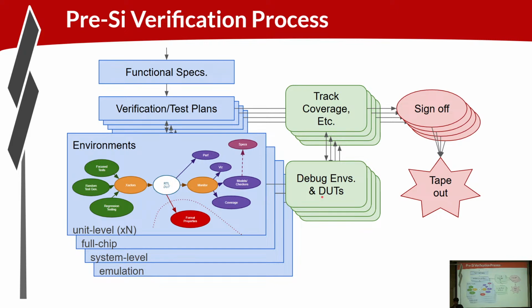Yeah, of course, there's the actual debug work, right? So you create these models in order to do debug. You're debugging not just the DUT, but also the environments themselves to stabilize all the modeling so that you can run all the testing. Once all of your test plans are complete, and you feel you have adequate coverage, and everything is signed off on all levels, you'll tape out the design.